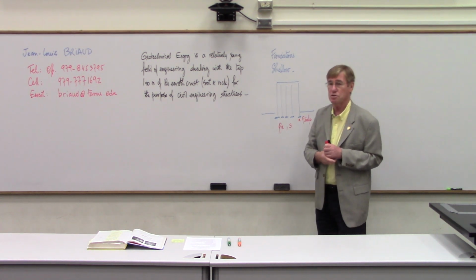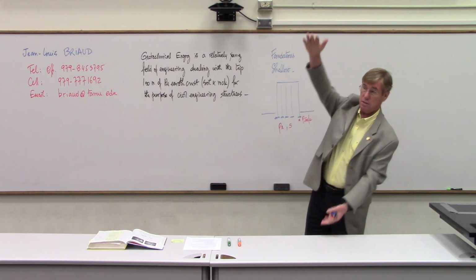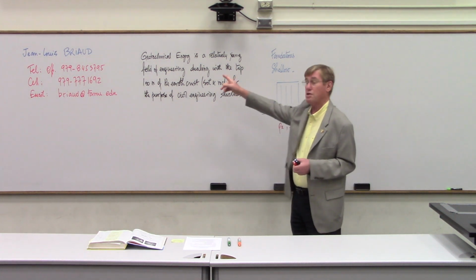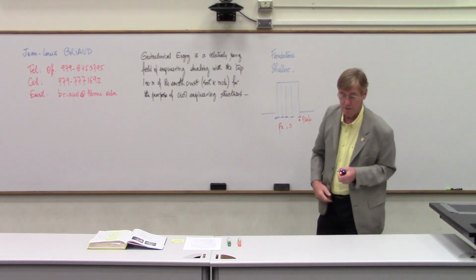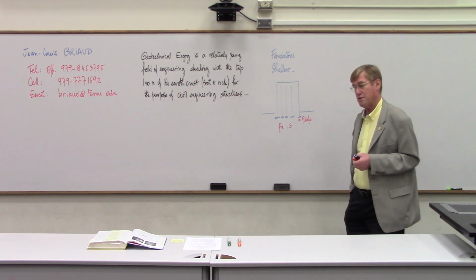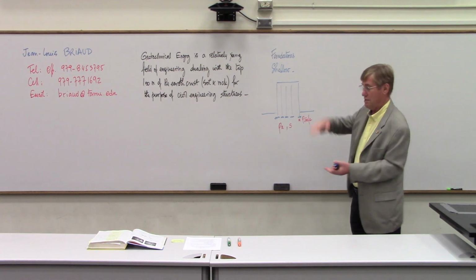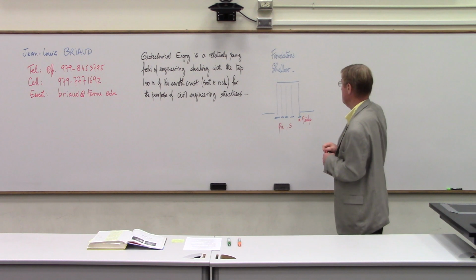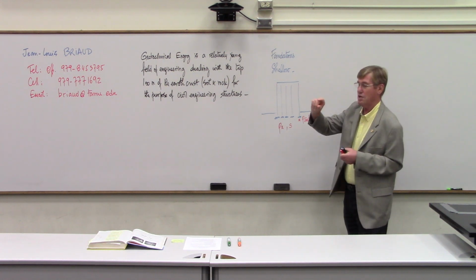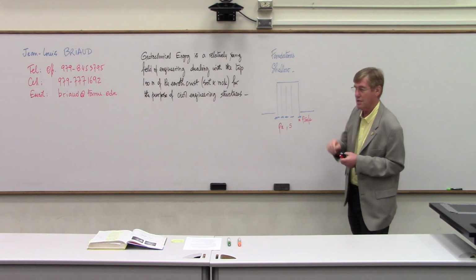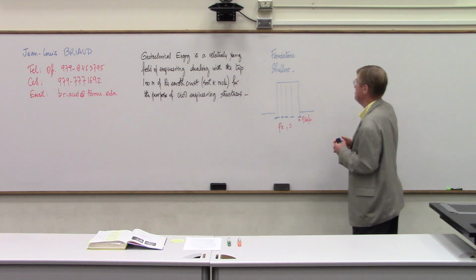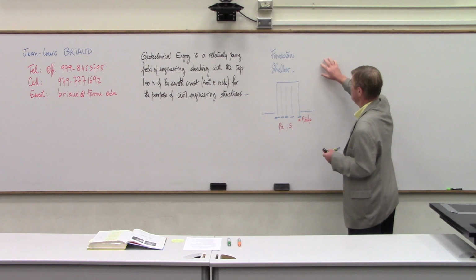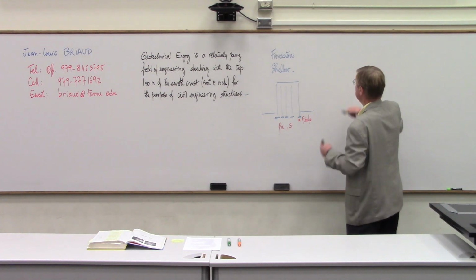Settlement of buildings is typically 20 to 30 millimeters. Although we have structures like the Washington Monument, we'll talk about it, that settled about 1 meter. The San Jacinto Monument, celebrating the 100-year anniversary of the freedom of Texas, settled about this much. Some of the buildings in Houston also have settled, but we tend to design for this kind of number. This can be debated. All right, so that's shallow foundations.